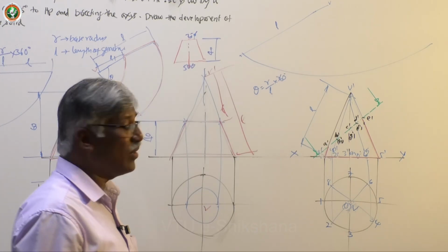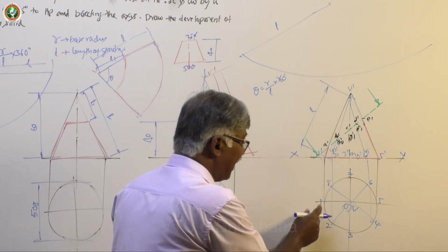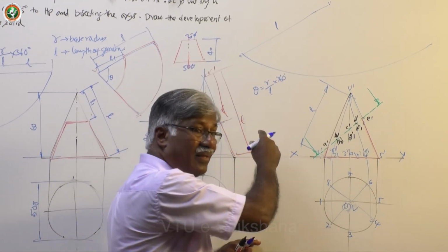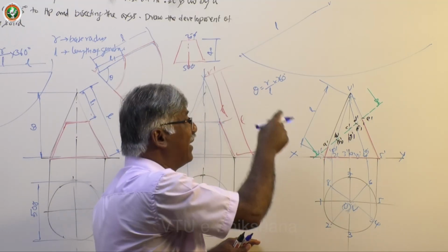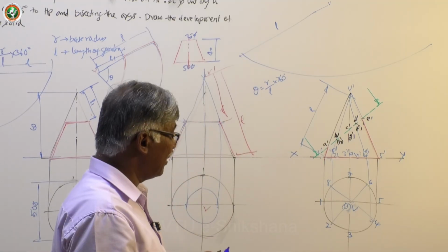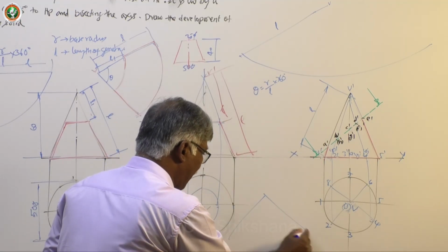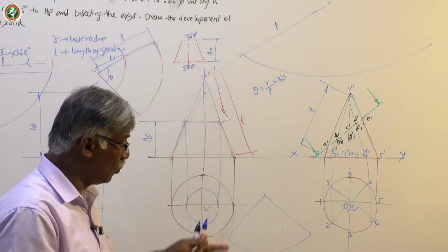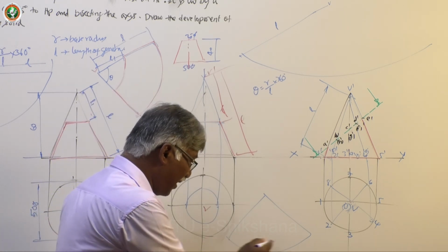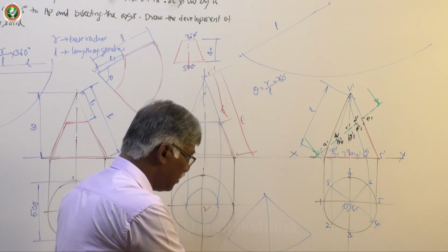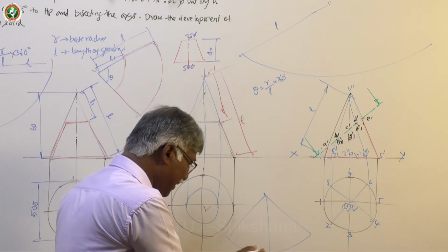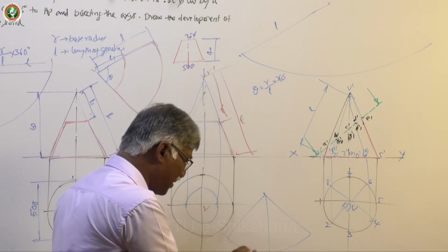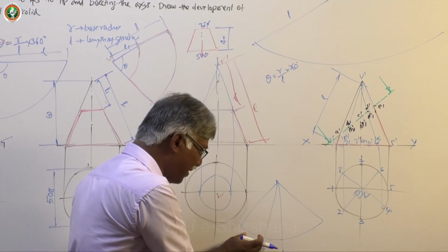Here manually what you do is you approximately calculate the value divided by 12 and take it, or how to divide the given angle into a number of equal parts. Say for example this, I have to divide this into 4. How to do it? Take more than half the arc length, draw 2 arcs. 2 divisions you have made. Again take this arc length, more than half of this, draw 2 arcs. Then take the same distance and mark here.